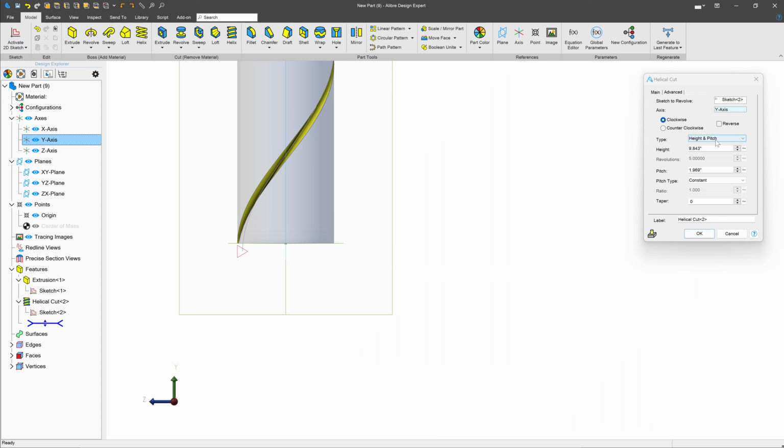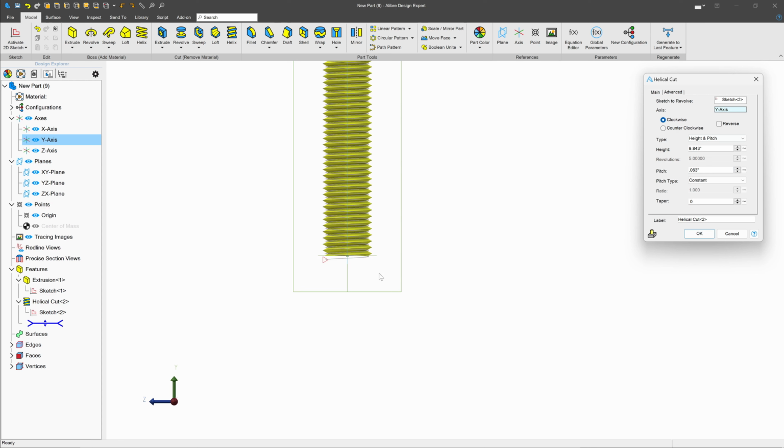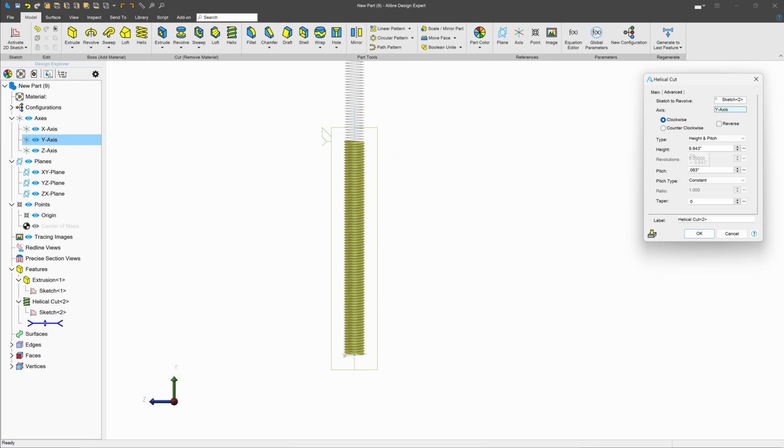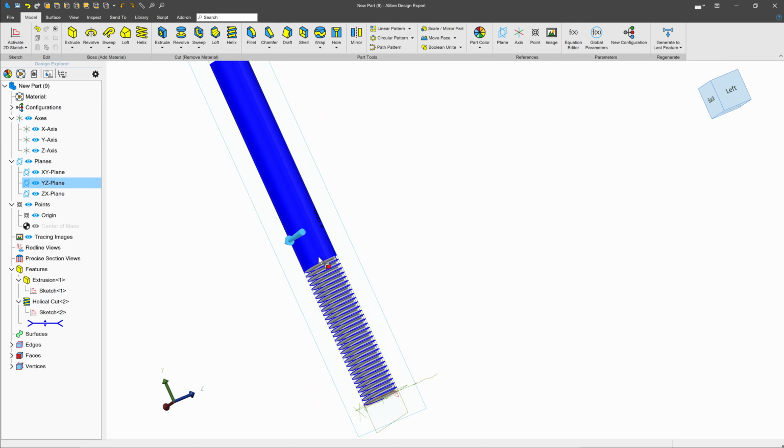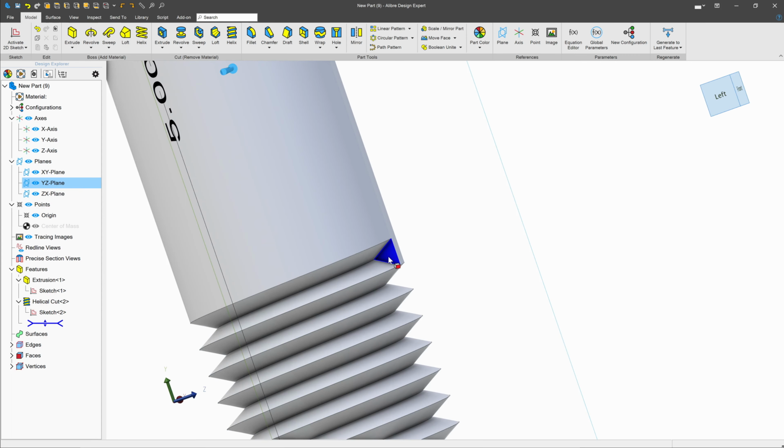Now, of course, we'll want our pitch to be defined, not as 1.969, which the 1969 Camaro was awesome, and that 1.969 makes me think of that all the time, but instead 0.0625, I think I set that dimension to be. And there we've got bolt threads, and we can change our height to be something like 2. All right, so we have a partially threaded bolt, just like that. Now you might say that that is an abrupt transition, and I wouldn't disagree.